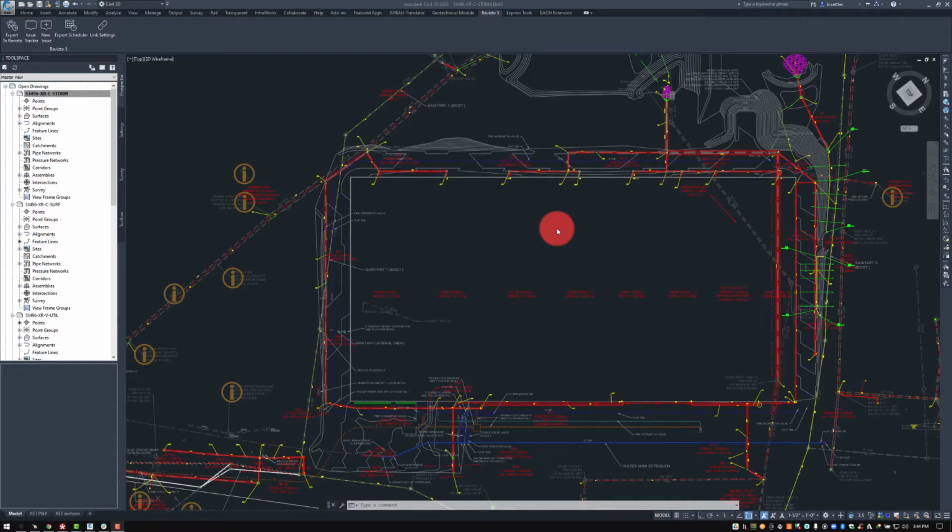So first, anybody that has used us in a civil capacity, which there are quite a few of you out there, knows that if we wanted to come from Civil 3D before, we would have to generate a 3D saved view with at least conceptual visualization. Or we would have to generate NWC exports, get those into Navisworks, and use that as a way to convert that 3D geometry into something that was readily acceptable by our software.